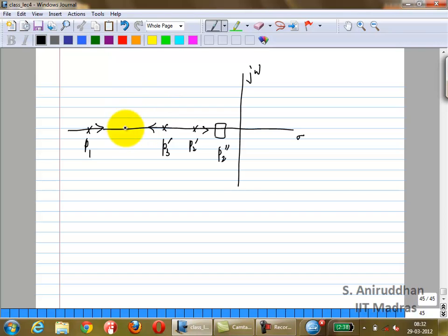Okay. So you'll get something like this. Okay. So if you look at the way the poles move in this nested Miller, they'll look like this. So you'll have a pair of complex poles and one dominant pole.